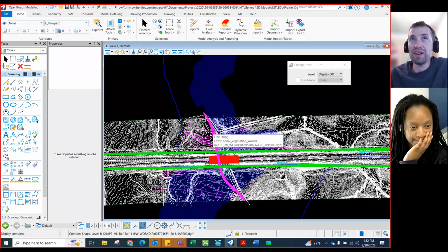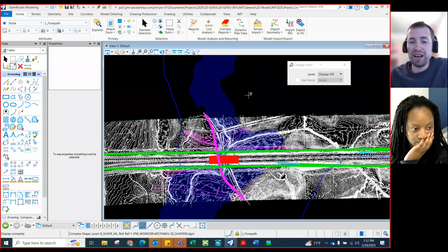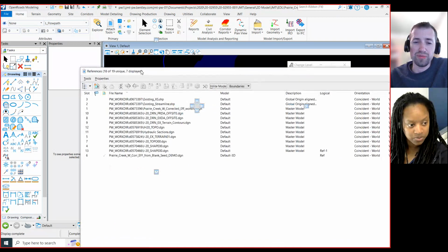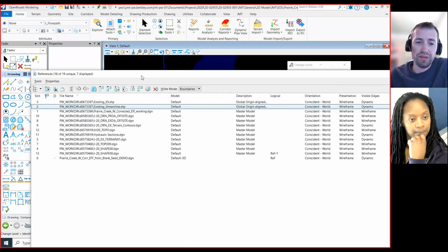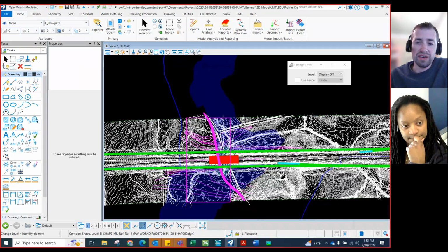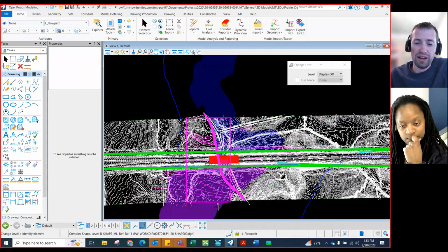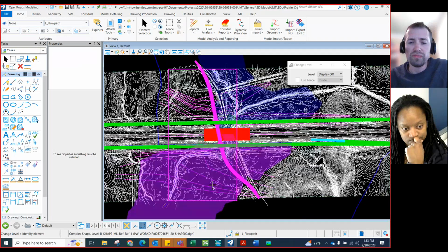In the email I sent about the FEMA base level engineering, in some of that PDF, I describe how you can export that to shape files. So I have exported their cross sections and their streamline to a shape file, and that's why I have that in the model.